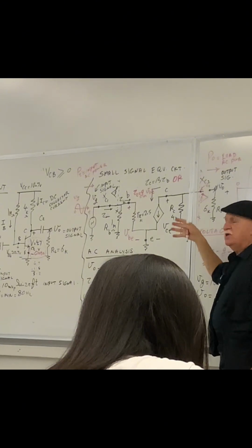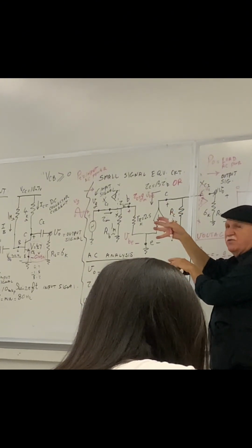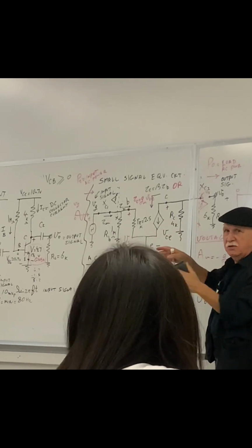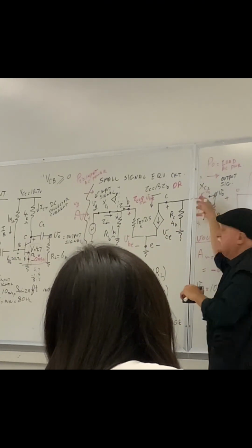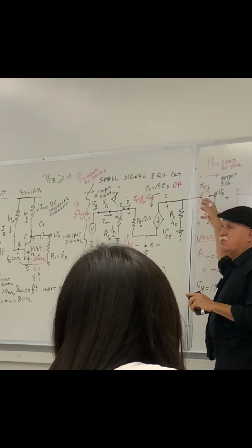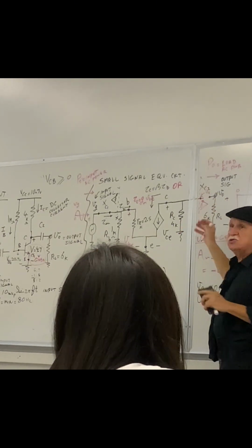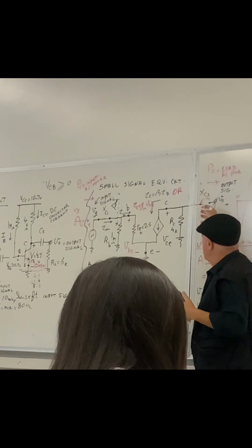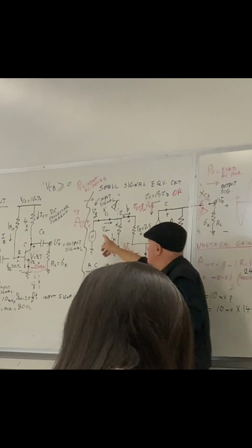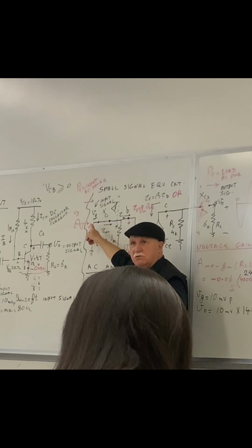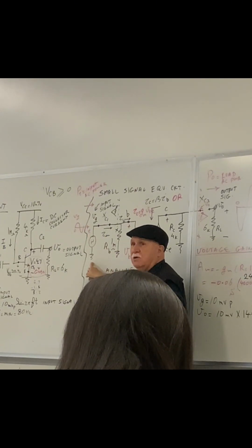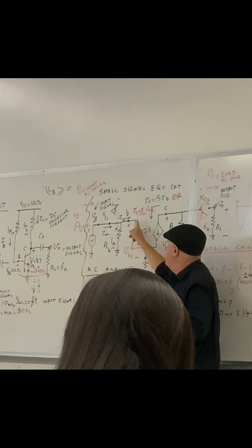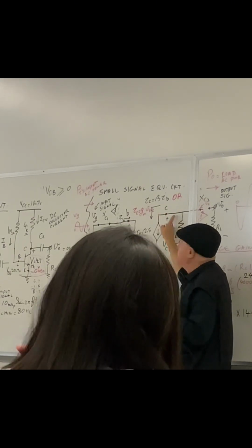How do we determine the Thevenin resistance? Do you remember the test voltage? To get it, I'm going to send in a test voltage and then see the result. But it won't go that far. Here's the reason. To apply the test voltage, you put that source to 0. Check here. If that is 0, then IB is 0, right? If IB is 0, IC is 0.